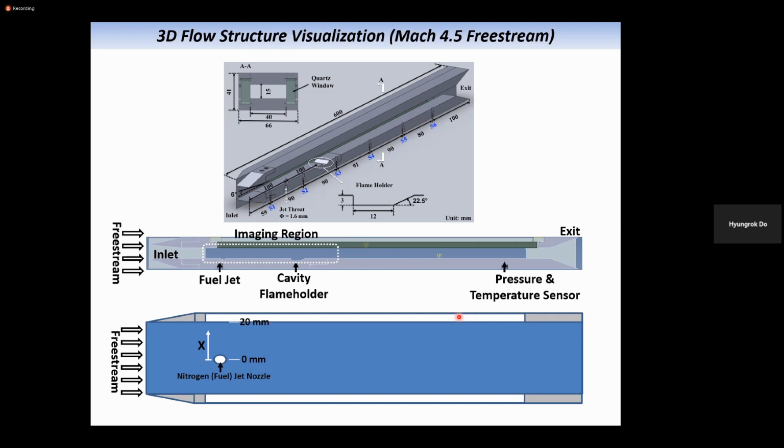without an optical access window. Once you have an optical access window, it will reflect and refract the laser light or the light source, the photons will be scattered on the surfaces, and your measurement will become much more complicated. But in most practical optical measurement environments, there will be a pressure and temperature difference across the optical access window. For example, your laser systems or sensors should be placed outside of the harsh flow conditions.